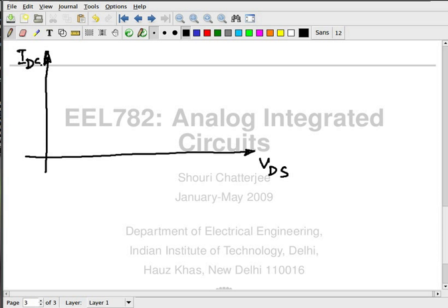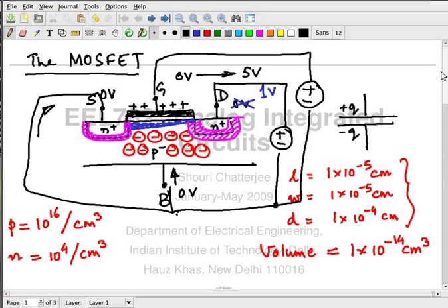Now, here I am going to point out that in modern transistors, modern MOSFETs, the gate is so thin, that layer of insulation material is so thin, this layer of glass is so thin, it's a few atoms thick. Okay, and when we talk about a layer which is a few atoms thick, few as in 5, 6, not even tens of atoms, then there is tunneling current from the gate into the channel. Okay, quantum mechanics comes into play, and strange things happen. Cat is in the bag, cat is out of the bag, etc. So, there is a small gate current in modern MOSFETs.